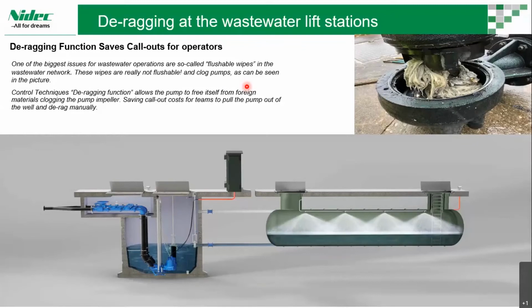It's a big problem because the wastewater systems are not really designed to deal with this. There's various pumps available that can grind the wipes. There's also some inline macerators that can sit in the pipes and grind up this stuff, but that creates other problems in blocking screens with smaller particles than the rags themselves.